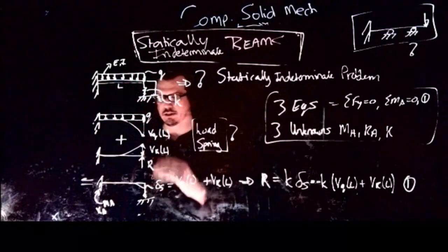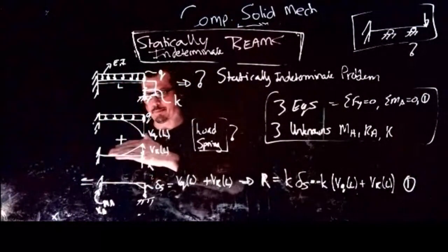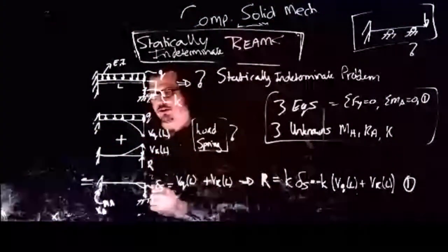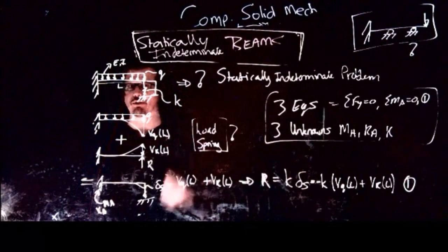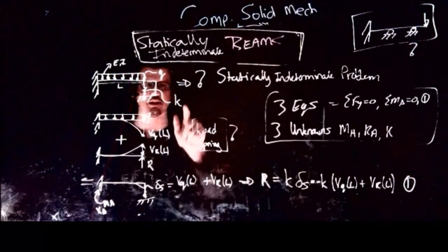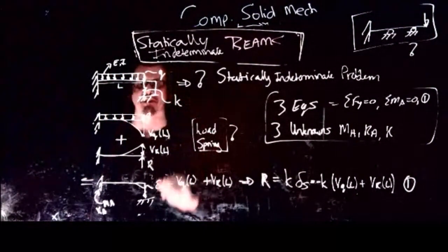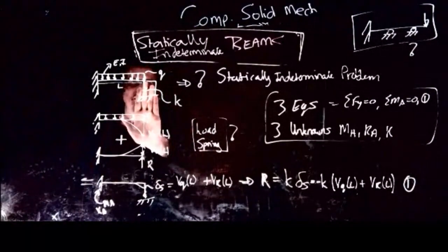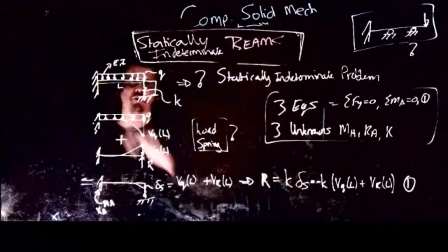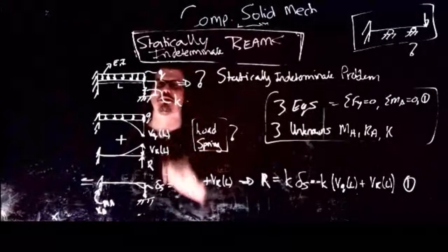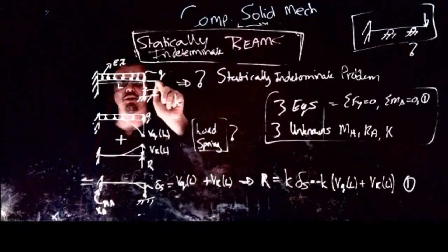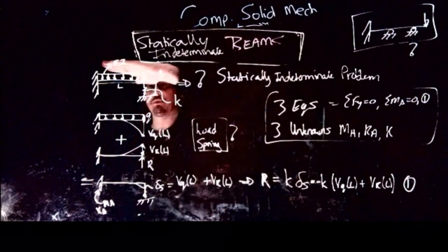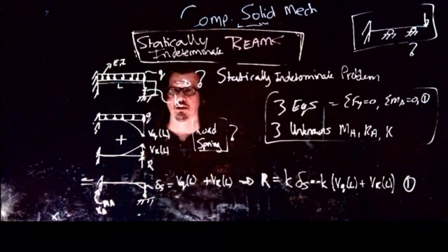And the reason for that is the force in the spring was dependent on how much things deflected. So it's a strong function of the stiffness. I went through this example problem yesterday where I said, let's imagine the spring stiffness being close to 0. Then essentially it's as if that thing doesn't exist and this thing can deform freely. The other extreme is to say, let's imagine the spring stiffness to be essentially infinite. And then essentially this is like a roller constraint that we had. And it means this thing will essentially just behave quite differently. So that's in essence where we are.